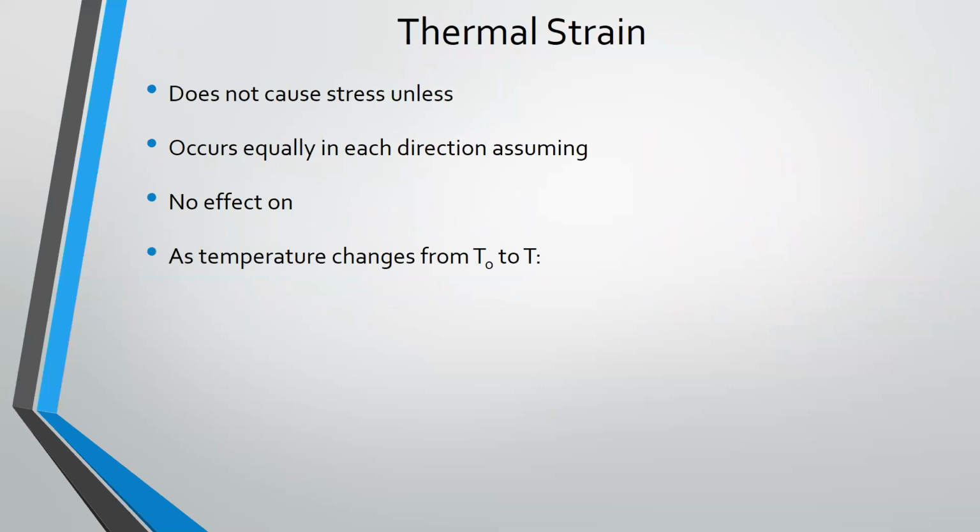So how many of you have walked on a sidewalk? Concrete sidewalk. How many of you have observed that there are, at regular intervals, like a divot that goes across that sidewalk? What is that for? Expansion. It's for expansion of that concrete. So as the temperatures increase, the concrete's going to want to expand, and that gap gives it a place to do that.